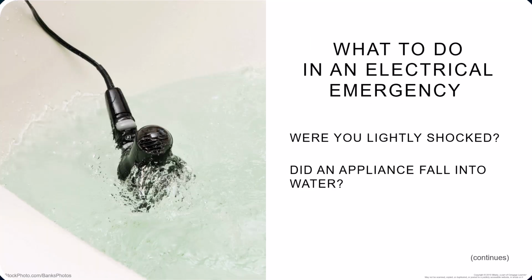Low voltage shocks are rarely critical, but they can be quite painful and dangerous to some individuals. If you receive a light shock sensation while using, turning on or off, or plugging in or unplugging an electrical appliance, you should stop using the appliance immediately and turn it off completely. Unplug it from the wall or turn off the circuit breaker to the outlet. Replace the appliance or have it repaired by an authorized repair representative. If similar issues occur with other appliances in the same outlet, discontinue the use of that outlet until it's approved by a certified electrician.